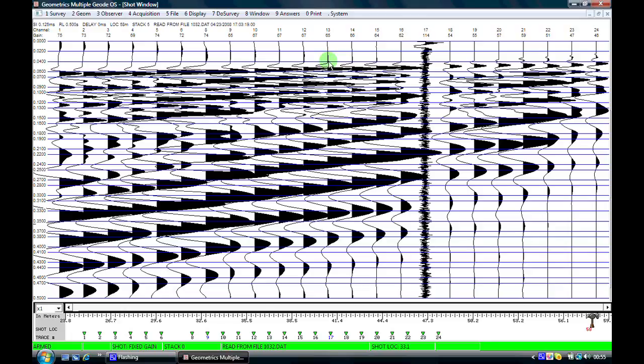In a seismic refraction data acquisition sequence, it is important that we locate this time for our first breaks as accurately as possible, because it's only by achieving high accuracy in this travel time that we get the best fidelity in our data analysis. So, as we're displaying a very long record length at the moment, 1/2 a second, and our travel times are only of the order of 0.05 of a second, probably what we need to do is expand our record.